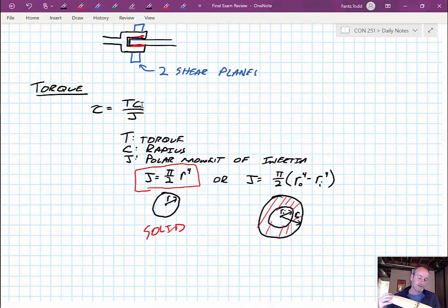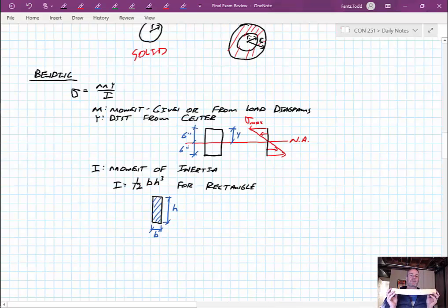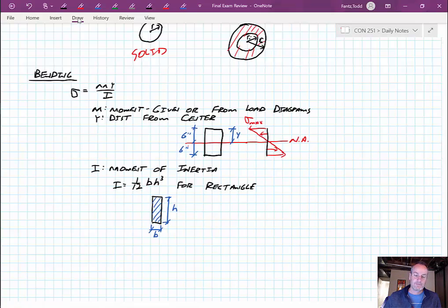What is our allowable shear stress? And so we can see if our drive shaft, or whatever's twisting, is going to break or not, right? The other type of stress we talked about was a bending stress. With a bending stress, we could have a positive bending like this or negative. But we had a basic equation. We once again have this sigma value, meaning it is an axial, a tension or compression type of thing.